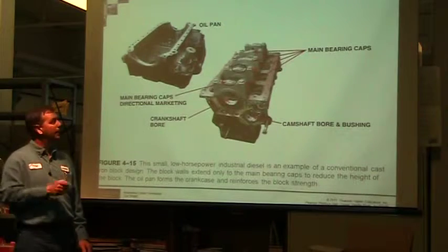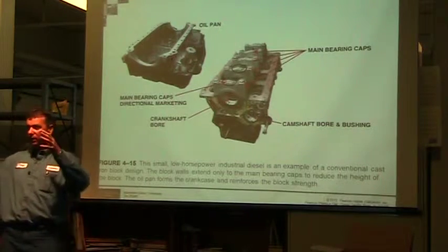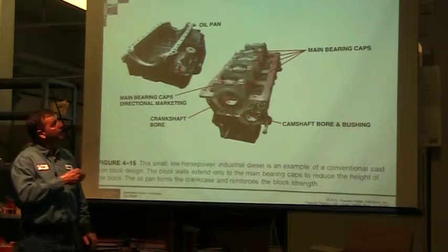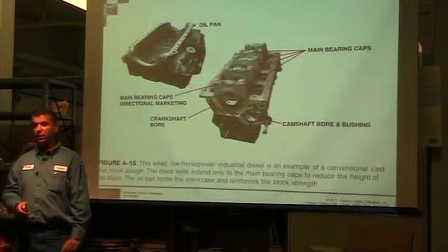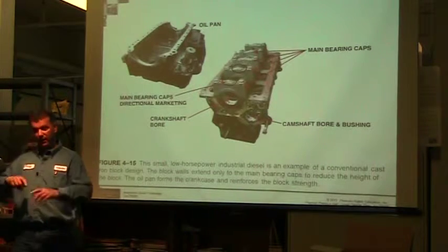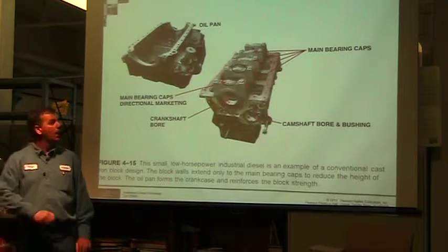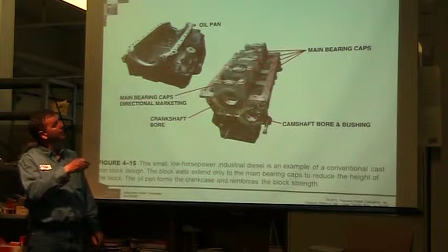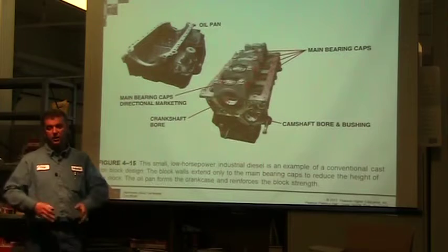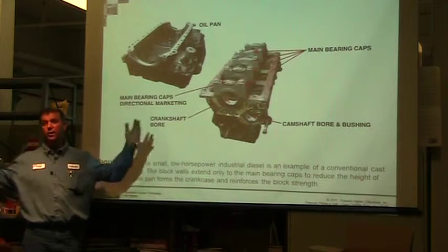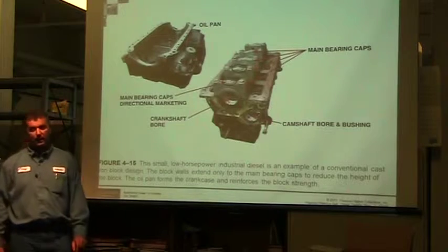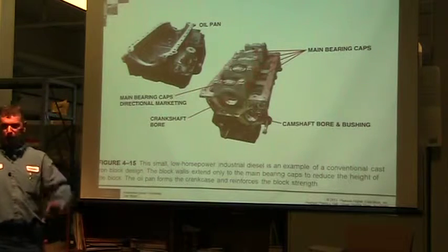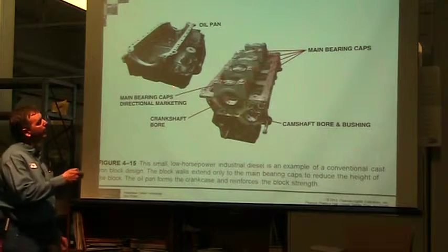We have an oil pan over here that came out of a reefer unit. So you're looking at over-the-road trucks that have a cooler unit hanging on the front, and because reefer units spend a lot of hours on the road, to get the oil change intervals extended out, they put heavy cast iron pans in there with extra space to double and triple the amount of oil in them, so they can go longer between oil changes. A lot of times they get left somewhere running for days and days, and then they travel around the country. People tend to forget about them, so they add extra oil.